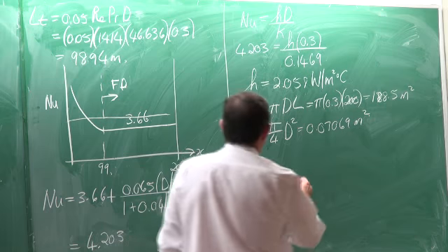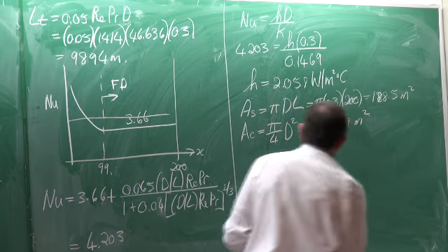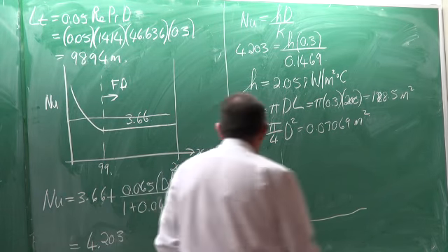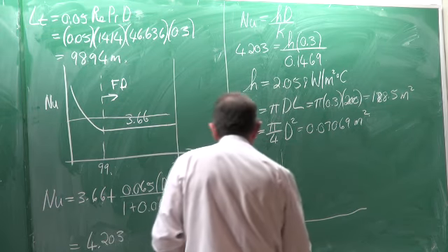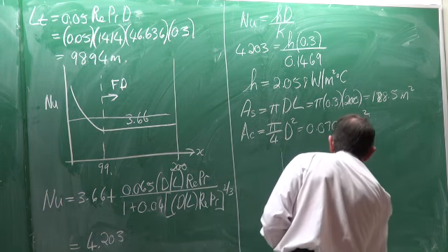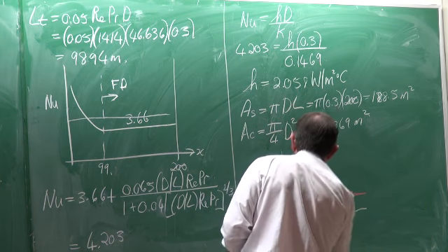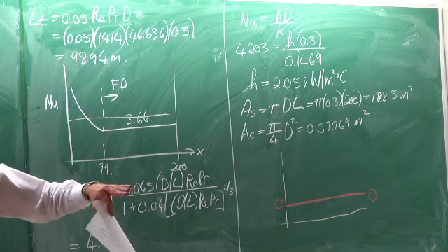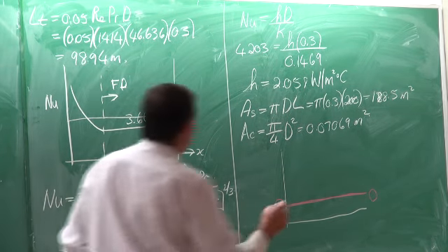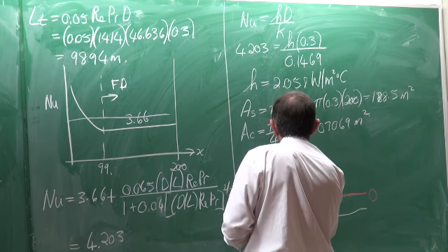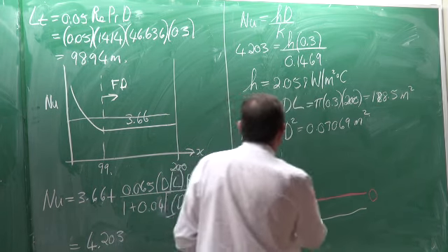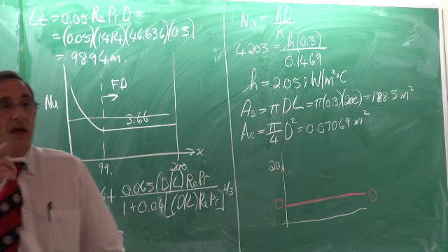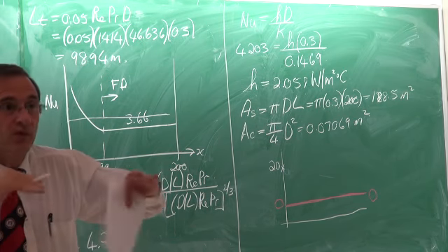Okay, so now with this type of problem, it always helps to draw yourself a graph of all the temperatures. What we have here is the icy water, which is at 0 degrees. The surface temperature of the wall should therefore be 0 right through. You agree? The inlet temperature of the oil is 20. So it is going to decrease as it flows through the tube, isn't it? And the problem that we have here is a constant wall temperature case.